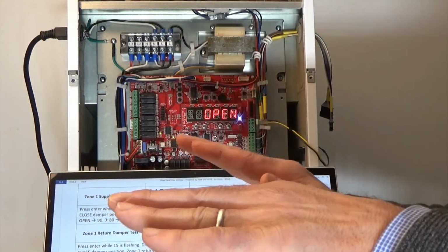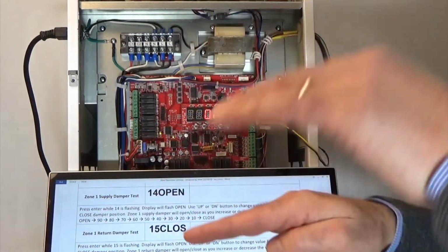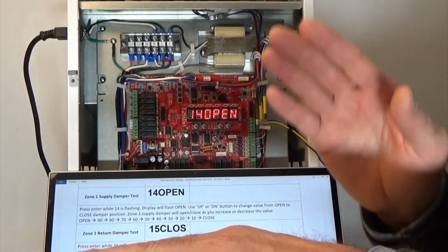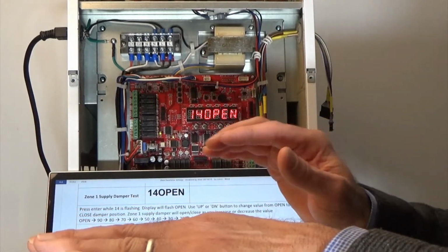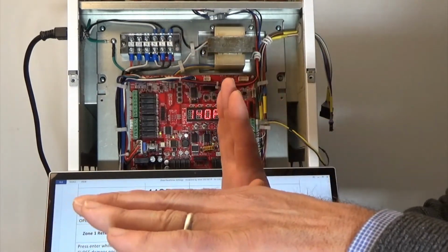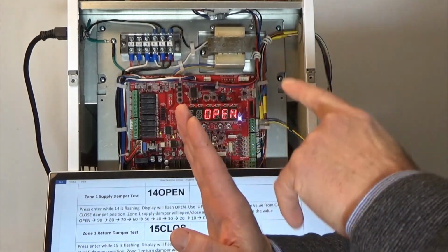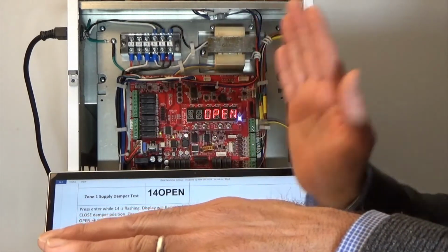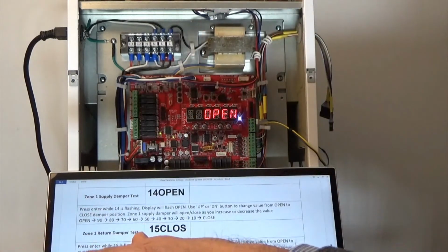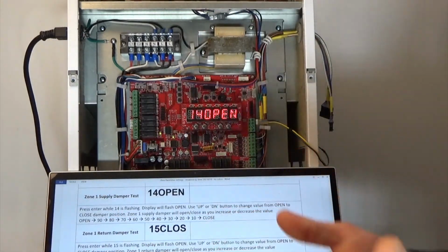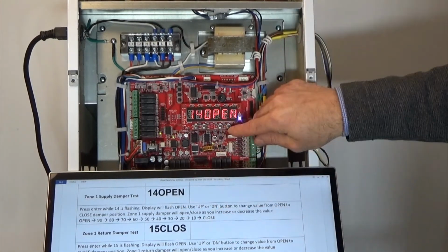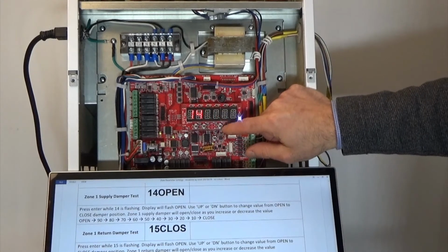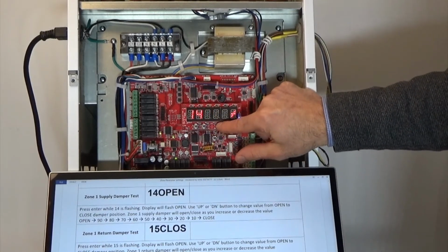So a lot of contractors mistakenly, if they're calling for zone 1, want to measure the power supplied to zone 1, but it's actually the opposite. We're actually going to close the damper for zone 2, so they're going to have to check that contact to make sure it's closing, because zone 1 is normally open, and it will keep open because we want to supply CFM to that area.